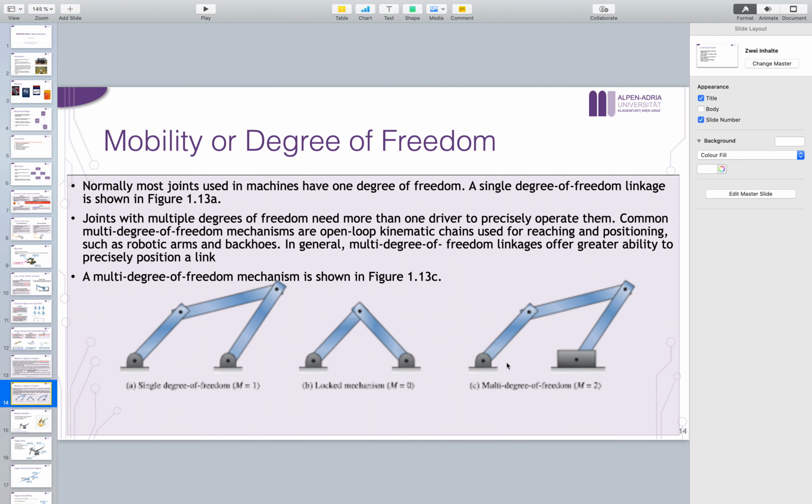How? Let's see. This is the first, basically 2 are cancelled here. The second 2 are cancelled here, so now we have 4. The third 2 are cancelled here, which means we have now 6. So we still have 4 to cancel out. That means we have here joints, because here I'm cancelling 2 and here on the slide I'm cancelling 2. That means this actually can do a kind of rotation here and can also slide. So it's basically how we come up to 2 degrees of freedom.